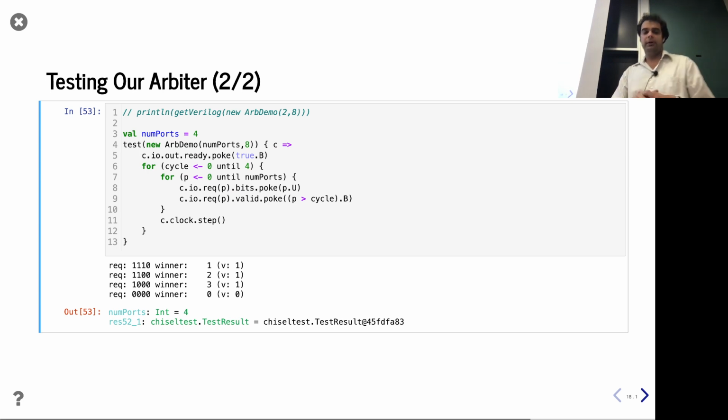Okay, there's multiple. If we're being clever about who wins, we can do this, right? But maybe we aren't always that clever. Maybe it's only some of them. Well, static priorities, right? So the same winner's going to keep winning. This is why you want a round robin one. But sometimes static's fine, right? Maybe you have a processor and you want the processor to have priority when it's having a cache miss to get that result back really, really fast for a load. You want to be able to outrank the prefetcher or something.